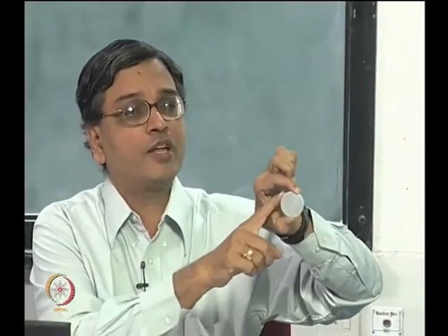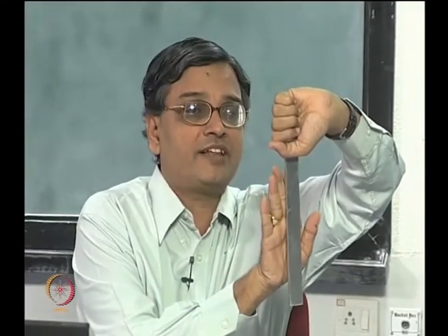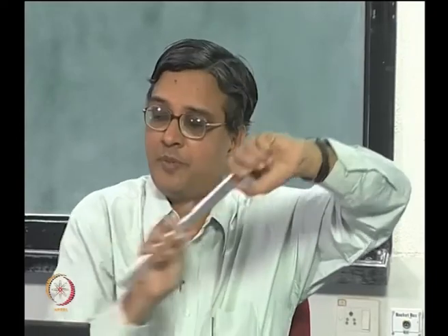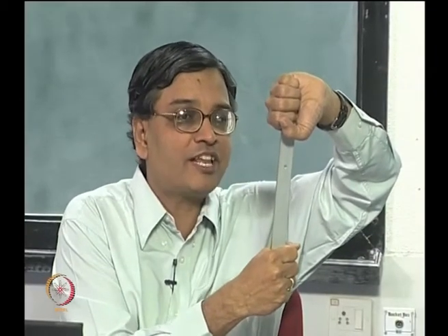On the other hand, other geometries, like a circular disc under diametral compression, you get a closed form solution from theory of elasticity. And compare, I have an axial member, I pull it, I can do it by strength of materials, but the same axial member, suppose I have a hole, I cannot solve it by strength of materials, I have to depend on theory of elasticity.